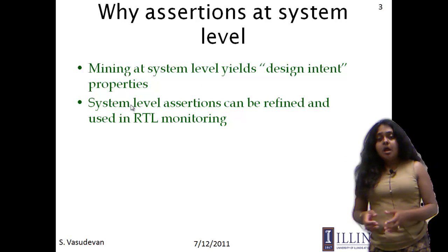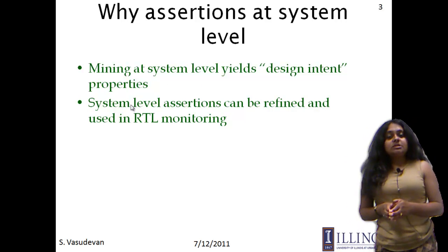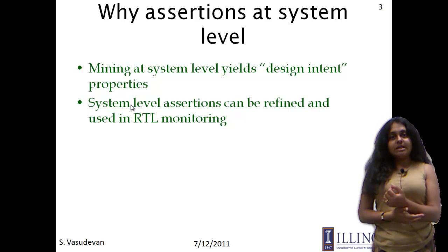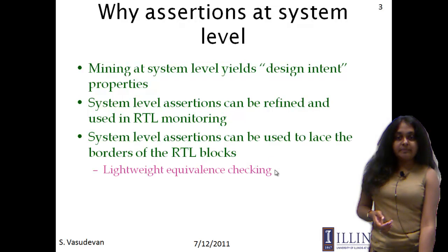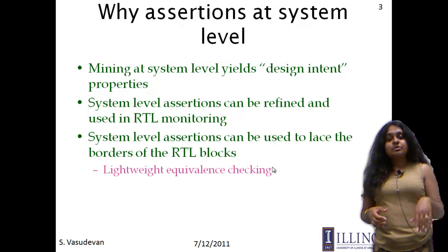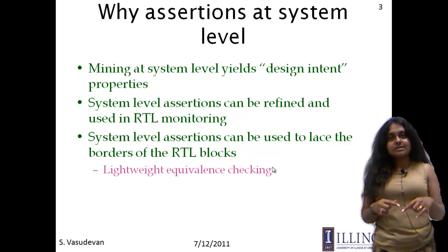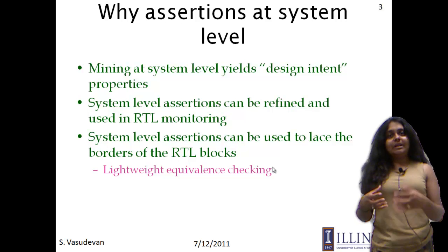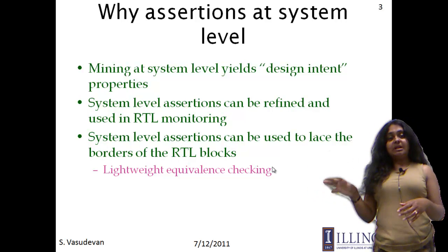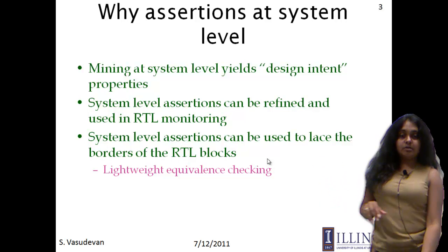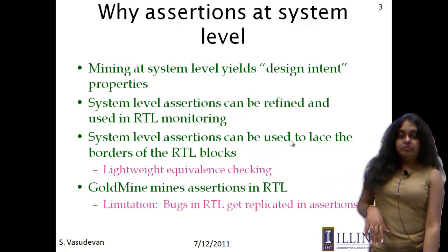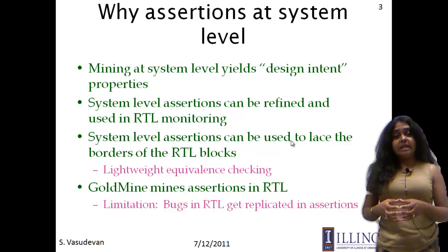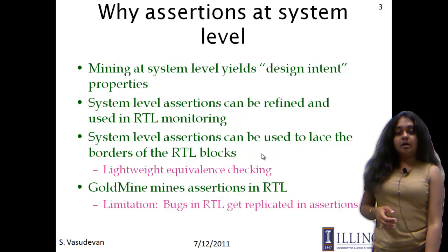The other reason is that system level assertions can potentially be refined and then mapped onto the RTL and be used in RTL monitoring. The system level assertions could also be used to lace the borders of the RTL blocks, and hence could be used as a mechanism for lightweight equivalence checking between the system level model and the register transfer level design.